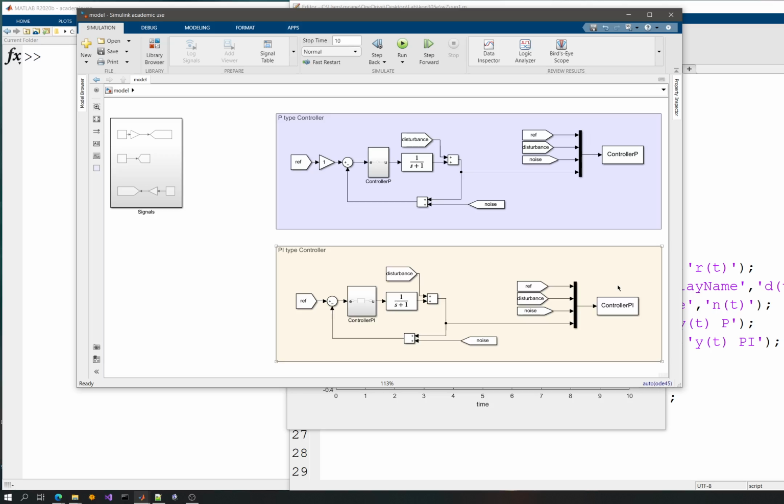And we tend to copy and paste most of the stuff, and it gives them silly names like controller 1, controller 3, controller 50, and then you are trying to get it working, but you might forget about something, and it's not really easy to see and debug that whole model. So using subsystems, some areas, and these labels is a better idea here.